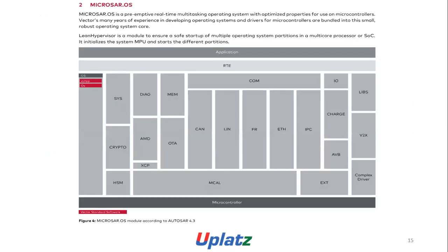academy.com. MICROSAR.OS. MICROSAR.OS is a preemptive real-time multitasking operating system with optimized properties for use on microcontrollers. Vector's many years of experience developing operating systems and drivers for microcontrollers are embedded in this small, robust operating system core. The Lean Hypervisor is a module to ensure a safe startup of multiple operating system partitions in a multiple processor or SoC. It initializes the system MPU and starts the different partitions.